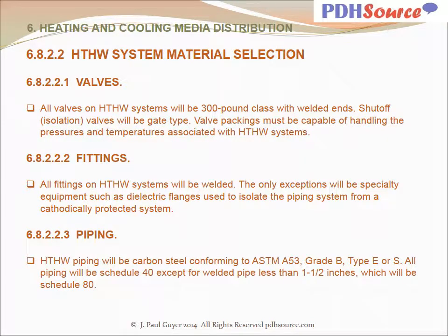With regard to selection of materials for high temperature hot water systems, all valves will be 300-pound class with welded ends. Shut-off or isolation valves will be gate type. Valve packings must be capable of handling the pressures and temperatures associated with the high temperature hot water system. All fittings on high temperature hot water systems will be welded.